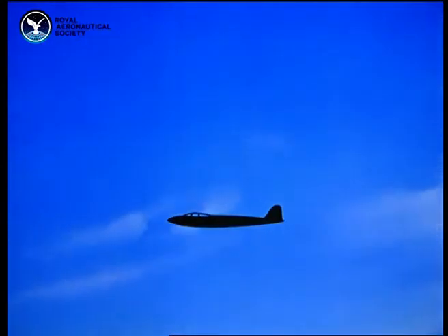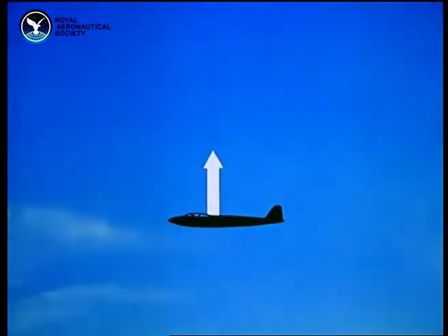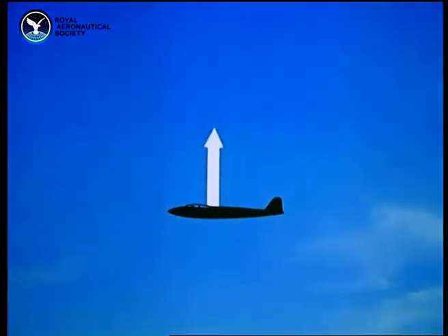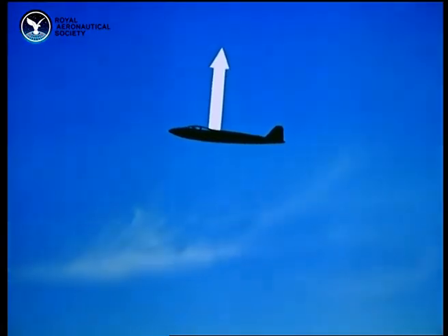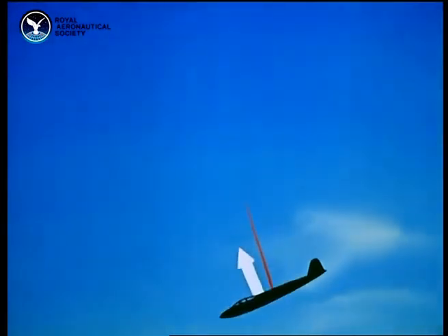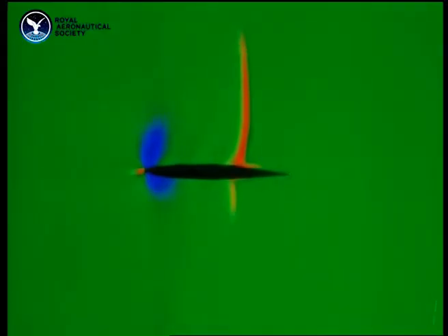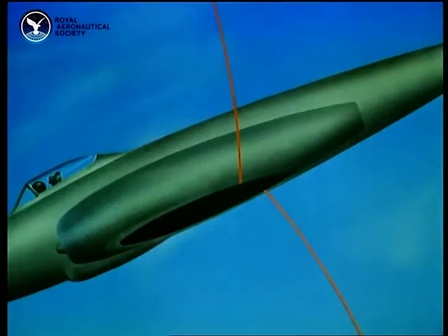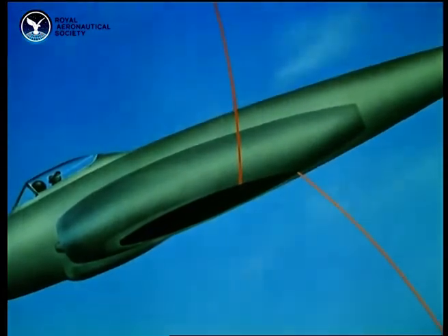The shock stall can also cause instability. For instance, changes in fore and aft trim. First, lift increases slightly just below the shock stall. This causes the aircraft to gain height. That is, assuming the pilot takes no correcting action. Next, at the shock stall, the sudden loss of lift puts it nose down. As the Mach number increases, the bottom shock appears and reaches the trailing edge before the top one. This forces the nose up a little.